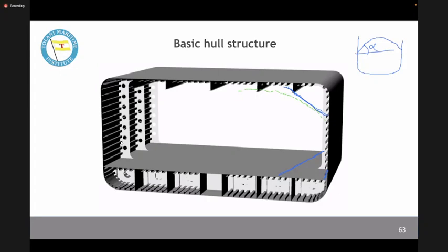Yes, sir. Okay. So this is the reason you have these two plates in a bulk carrier. When it comes to an oil tanker, it is relatively easy to find out if you are looking from outside, because on the decks you will have no hatch covers, only mostly pipings. When it comes to a general cargo ship, you have a twin deck. Almost no other types of ship will require a twin deck.